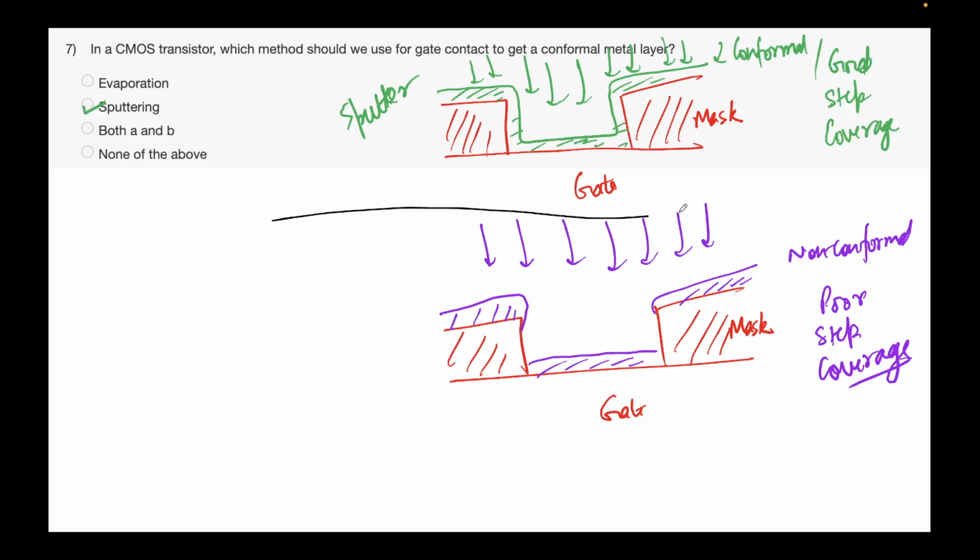Okay, next we want to make 3 micron gates. This is actually a realistic problem. In a lab we have 3 micron gates. Which instrument should we use to get faster and maximum throughput? Okay, 3 micron gates I can make through all of these techniques: e-beam lithography, deep UV, and optical lithography. All of them will give 3 micron gates. Okay, but we want faster.